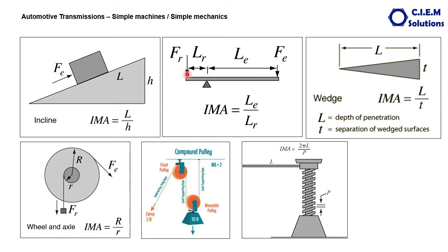The force is being lifted here. Force applied to lift this load. F4 is nothing but the load with this smaller distance or with this height, whatever may be. Here the mechanical advantage is the length of this lever from this pivot point, that is LE, at the end of the effort applied, divided by the length of the lever where the load is being lifted, LE divided